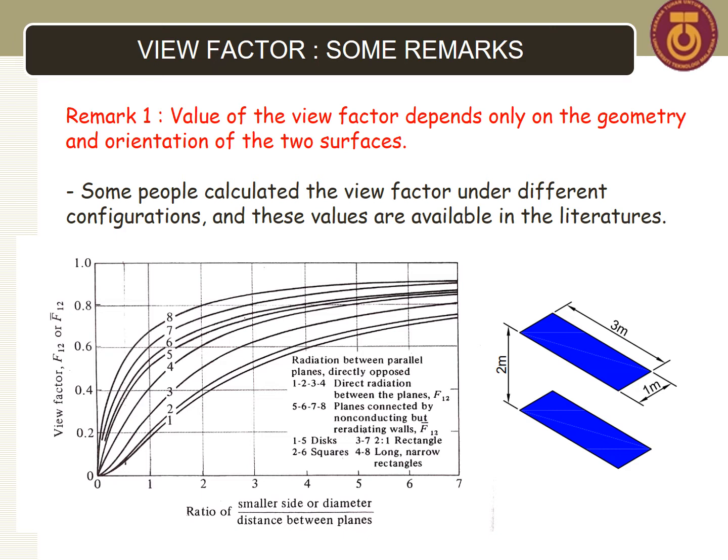If we halve the distance between the two planes from 2 meter to 1 meter, then your x becomes 1 divided by 1. So here you will start from 1, then drag it to curve number 4. So you will get almost double. The F12 value will be double.